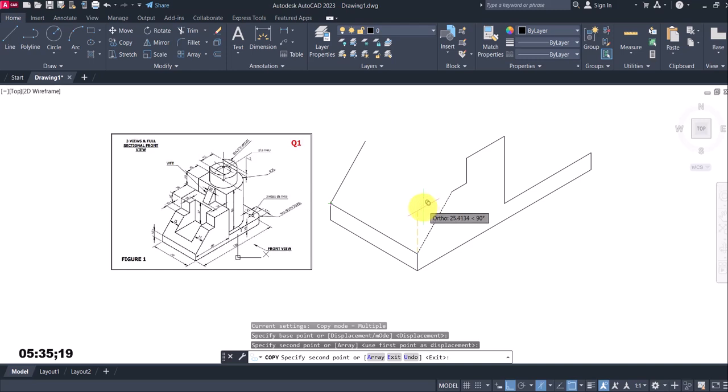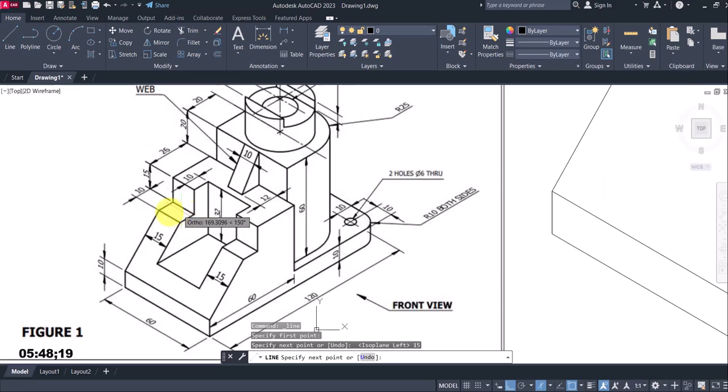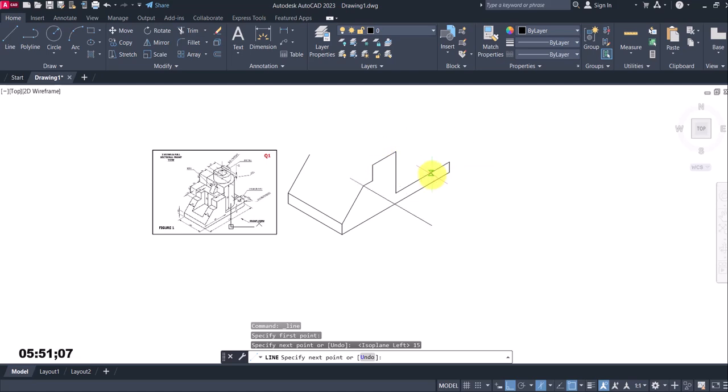Okay, all right, so from here I will continue with my line. This is 15, F5, 15, and this is 10, F5 again to change my direction, 10, then I'll snap here. I'll continue from this end, the same 15, F5, 10, F5 again to change direction, done. This direction 15, then I can snap to this point.